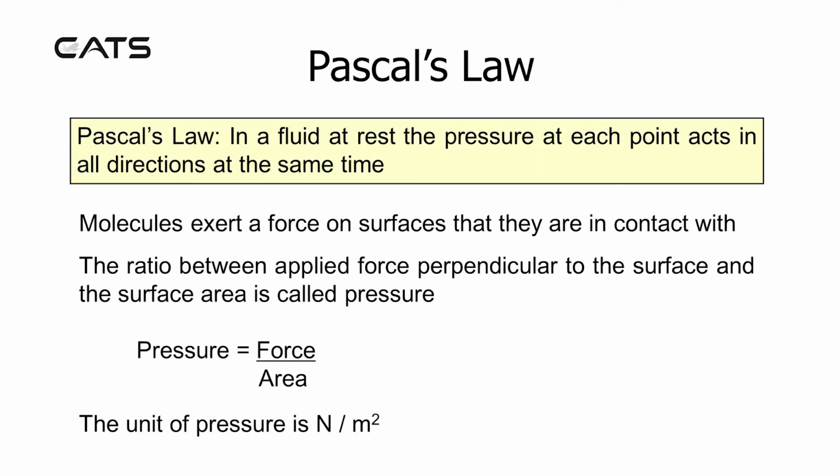Pascal's law. In a fluid at rest, the pressure at each point acts in all directions at the same time. Molecules exert a force on surfaces that they are in contact with. The ratio between applied force, perpendicular, that's right angles, to the surface, and the surface area is called pressure. Pressure equals force over area, and the units are newtons per metre squared.